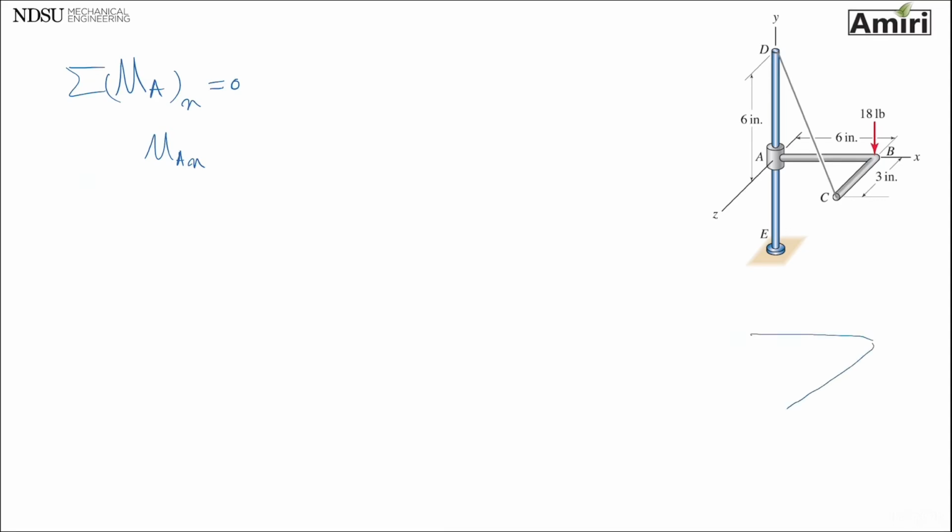Let's look. The vertical component of T, which is, oh, that's y. Okay, because for a second I was like, why is that negative? No, that makes sense. The y, which is 0.667 times 27 pounds. That's my T. That is the only force that I see causing rotation about x-axis.